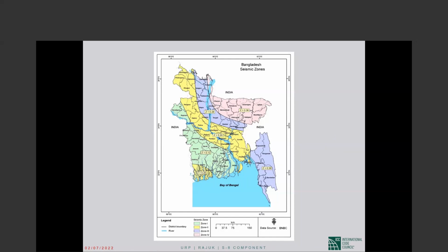Okay, Dr. Ghosh. If a shear wall is constructed as remedial measure for an existing building up to first floor from ground and doesn't continue above, will it be considered as out of plane offset irregularity? How is it out of plane? I don't know.